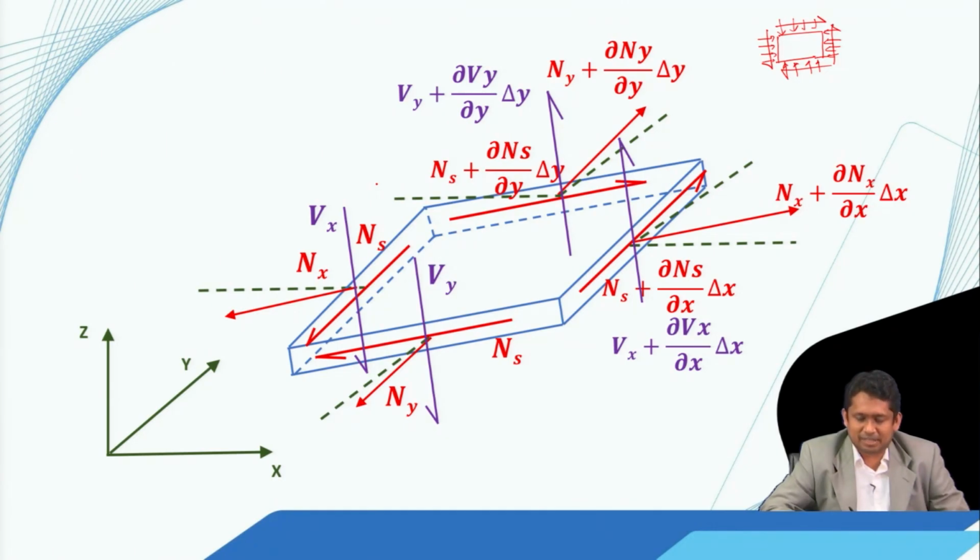And that's how the difference comes between what we did previously last week and this week. Last week, our goal was to study the static deformation, and we wrote the governing differential equations. For writing the governing differential equation, we studied the stability of the flat plate, the initial flat configuration. But here we have to incorporate the destabilizing effect of these shear and normal forces. So for that we need to study it.